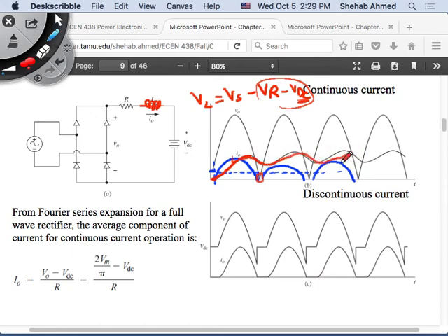Right? If you increase the DC voltage, what will that do? Will it take longer for the voltage across the inductor to rise high enough? Won't it take longer for the voltage across the inductor to get to a higher positive value? So then the current won't it fall more? It will fall quicker. The current will fall quicker if you increase the value of the DC voltage.